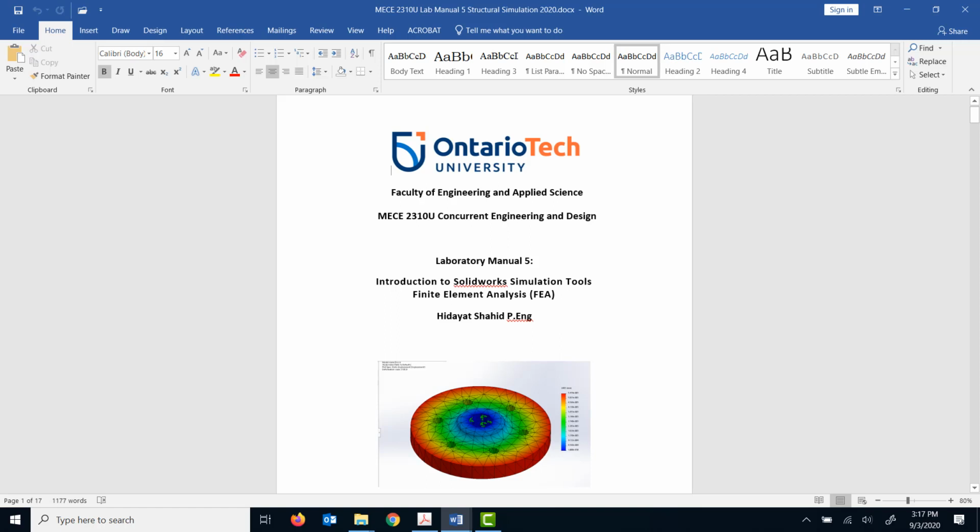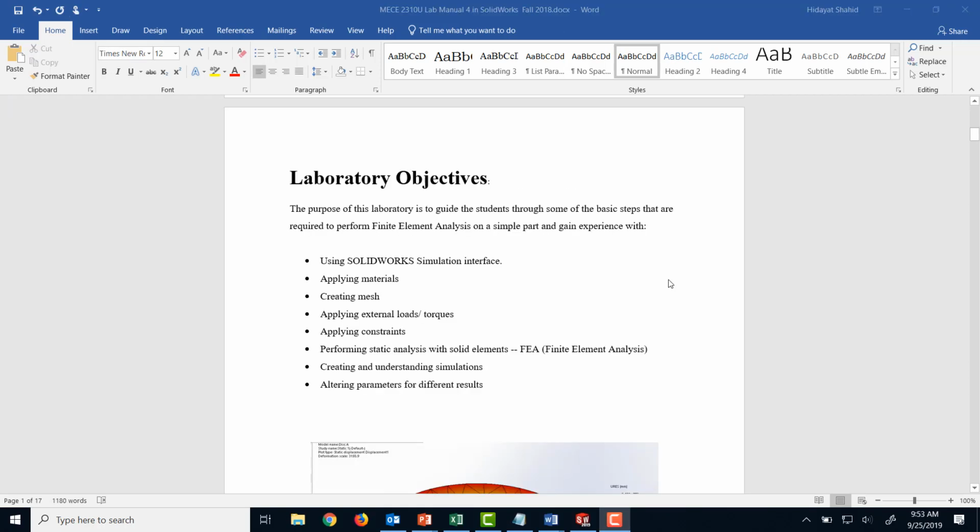The steps that are normally required to do finite element analysis: first of all, you define the geometry of the problem, then you assign some materials, and then you create a mesh. Basically what you're doing is dividing your larger object into small components, and then on that object you're applying the laws of physics. For example, conservation of energy and conservation of momentum, and then you're tying those down with the material behavior and other constraints such as compatibility and others.